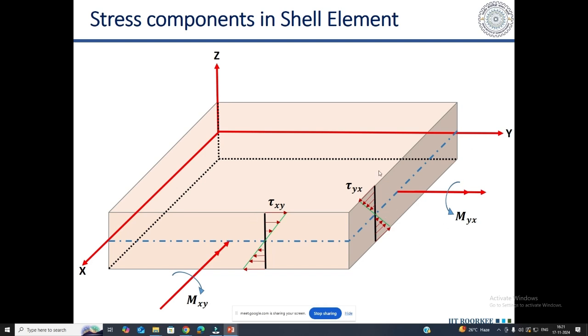And both of these stresses are now not out of plane, these are in plane again. In plane means the arrow direction is not going away from the plane surface, it is within the plane surface only. In the first case it is still in the x plane, in the second case it is still in the y plane. So it is coinciding with the plane where the movement is acting. That's why these are in-plane stresses, and both of these are shear stress again.